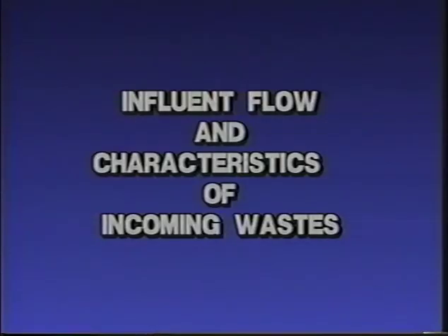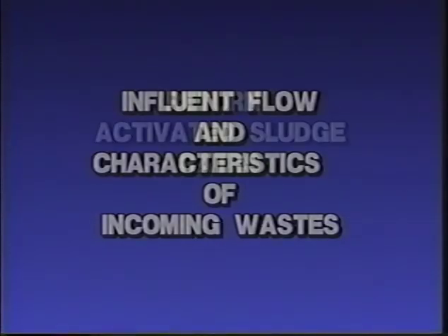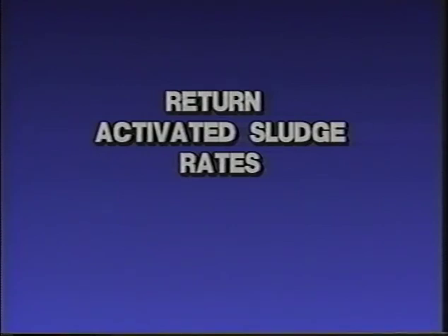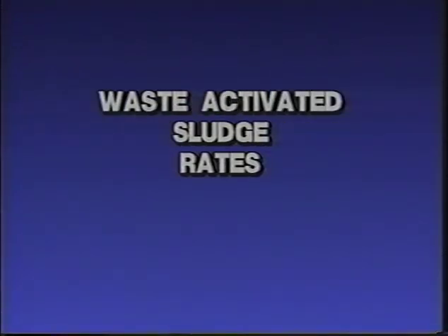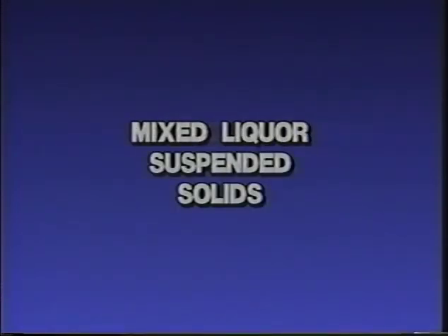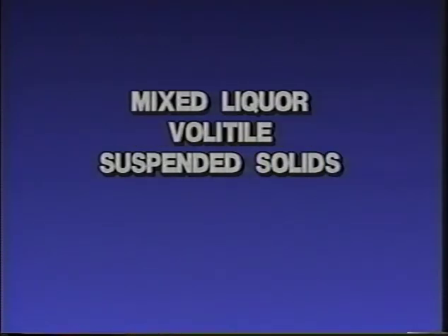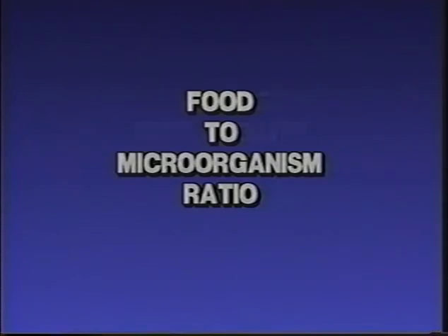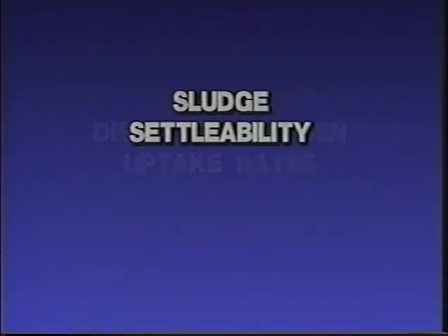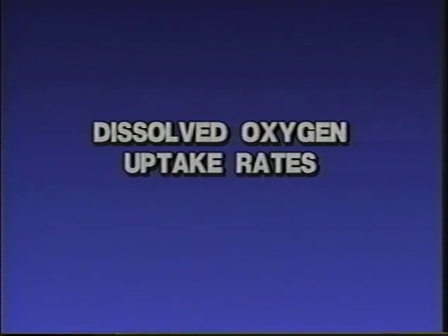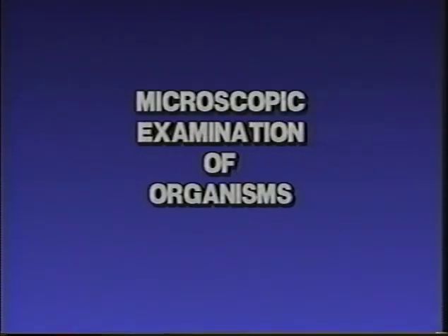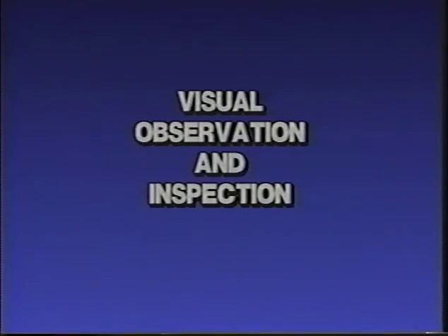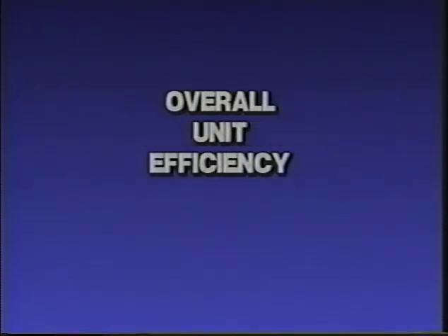influent flow and characteristics of incoming wastes, return activated sludge rates, waste activated sludge rates, dissolved oxygen, pH, temperature, mixed liquor suspended solids, mixed liquor volatile suspended solids, mean cell retention time, food to microorganism ratio, sludge settlability, dissolved oxygen uptake rates, microscopic examination of organisms, visual observation and inspection, and overall unit efficiency.